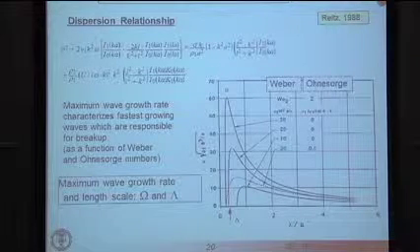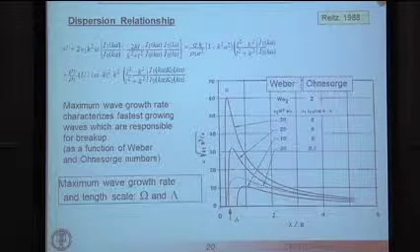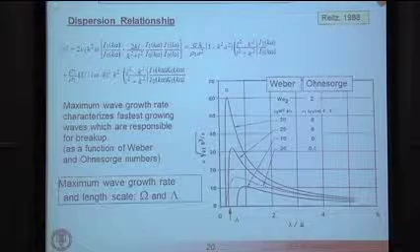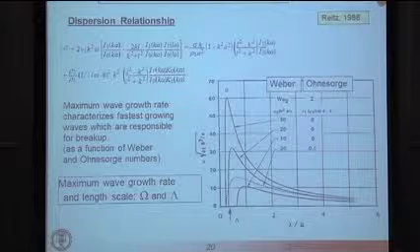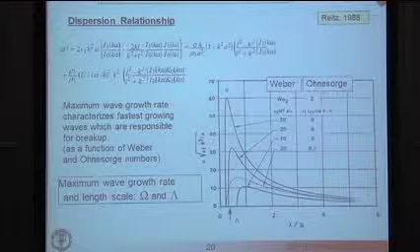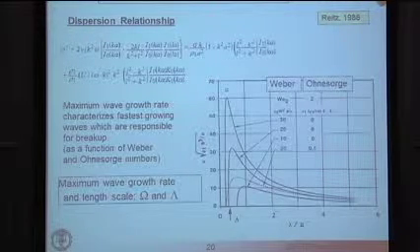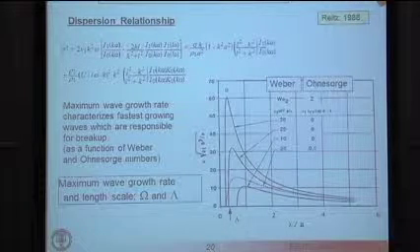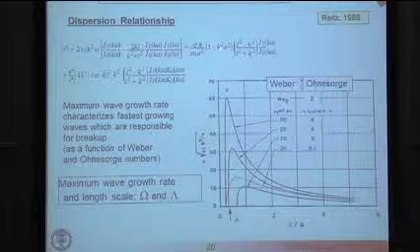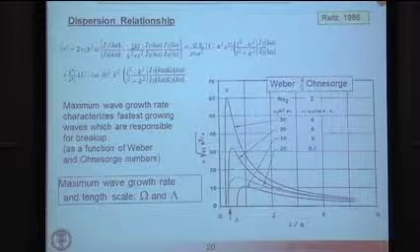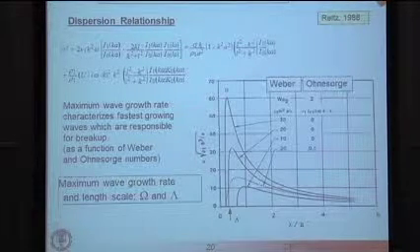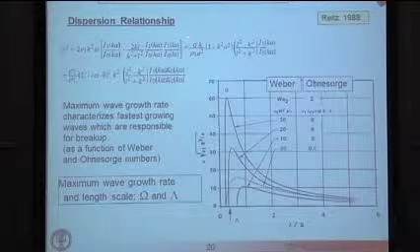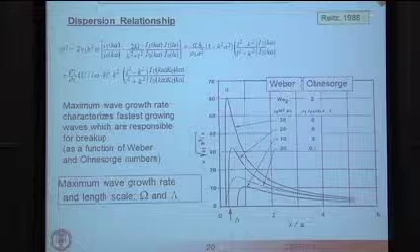So this dispersion equation actually is very rich because it describes all of those regimes of breakup that I discussed before. For example, if there's no effect of the ambient gas, you can throw away this term. If you throw away viscous terms, then you just get Rayleigh's result, which is shown over here. When Ka is greater than 1, you have a regime change from long wavelength waves to short wavelength waves. So all of that shows up in this dispersion relation.